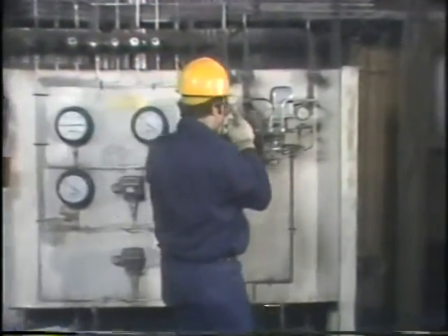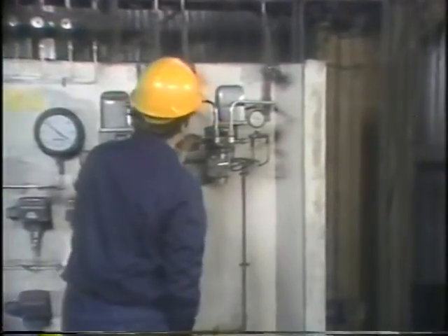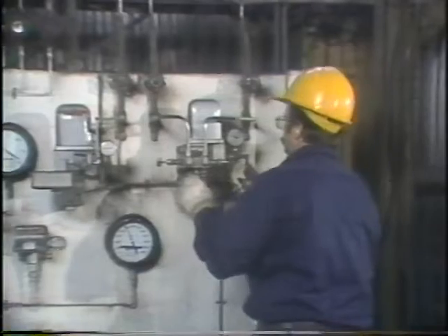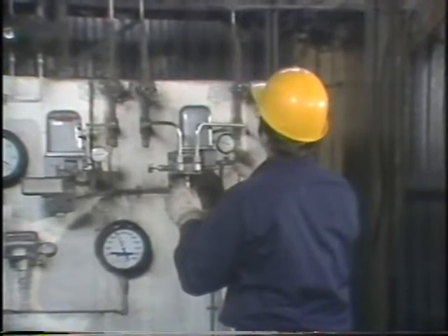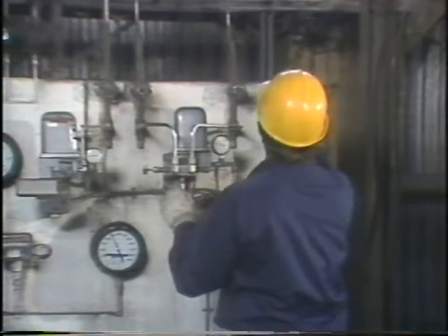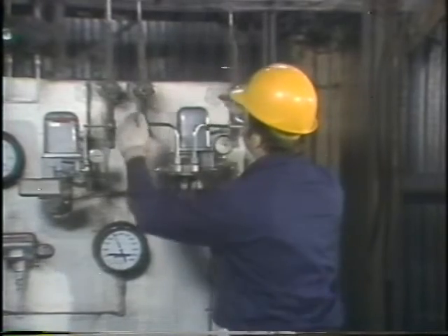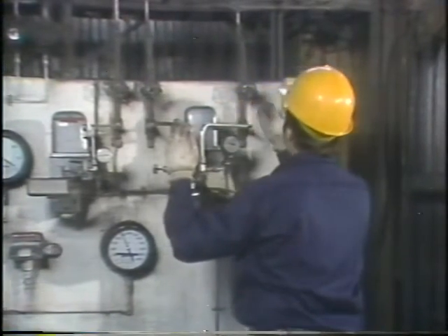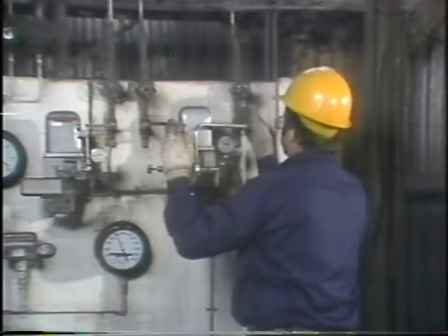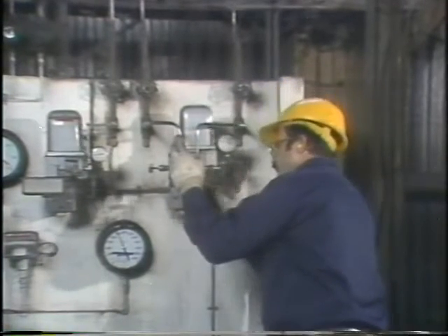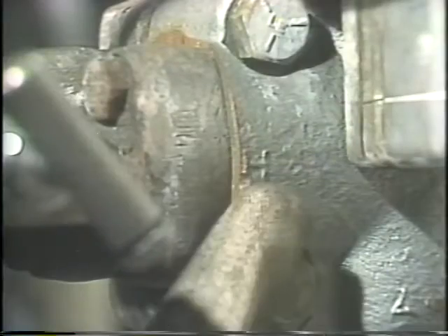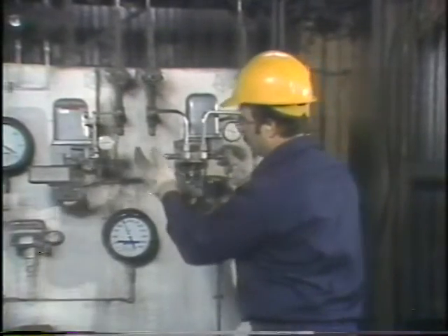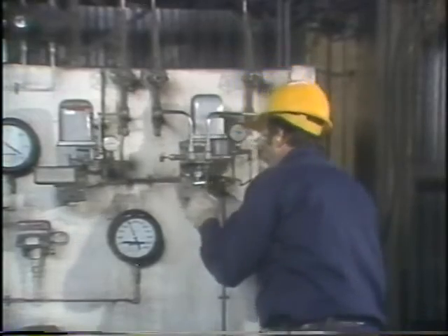Let's see how this thing's connected to the process. The gauge. The process pipe runs overhead, and tubing comes down here. This is one root valve, and the line to the transmitter. This is the other root valve, and the line to the other side of the transmitter. See, yes, here's an H. This is my high side, so that makes this the high side valve, the low side valve, and the equalizer.